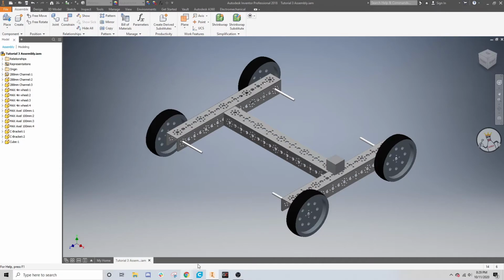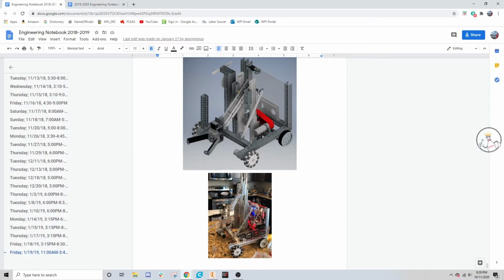So this is an example of my first year of FTC. This robot CAD and this robot. As you can see, it's pretty accurate, except for obviously the electronics in the back and this number plate. But other than that, that's all I can really notice for the differences. But this was a robot that I CAD'ed as we went, and as a result, the robot tended to do wheelies because all the electronics were in the back, which means there's a lot of weight in the back, which is also directly over some motors.